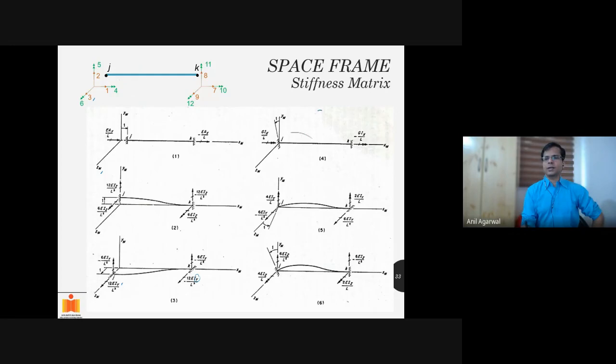Here, when we are using Ix, we are not assuming it to be an I section, because if you start with an assumption of an I section, you cannot avoid warping. Warping terms will not follow this kind of stiffness terms. Warping terms are more complex. So for the purpose of torsion, we are assuming a circular cross-section, or we are ignoring the warping effects completely, by some magic. Then you can come up with these simple terms for torsion.